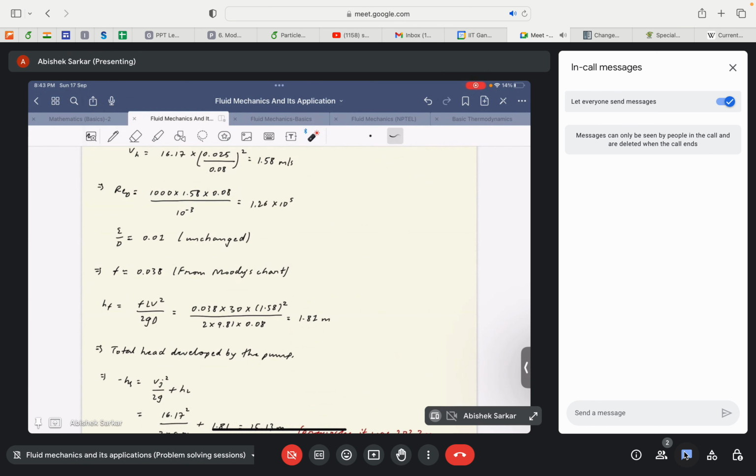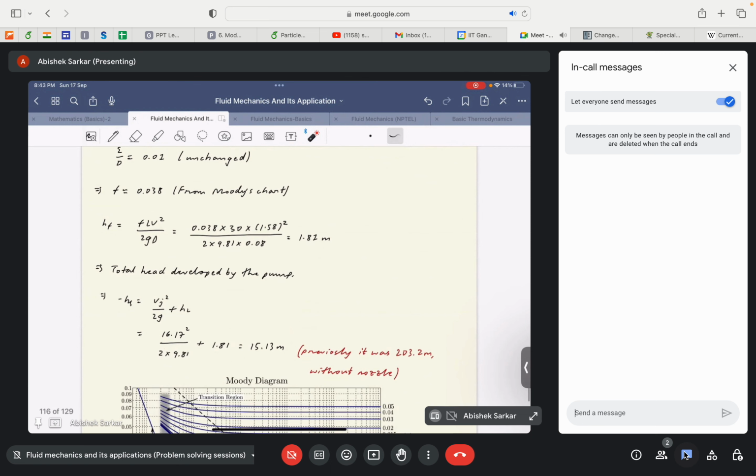And this low velocity requirement in the pipe thus results in a very low head loss, low frictional loss in the pipe, and thus a comparatively very low pumping power is required to eject the fluid from a lower elevation to a higher elevation, so that the fire can be extinguished. So that's a very important conclusion that we get. That's why I found this problem very interesting, personally also.